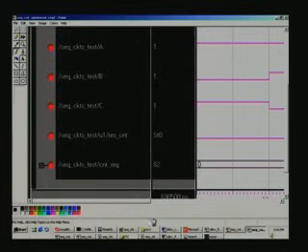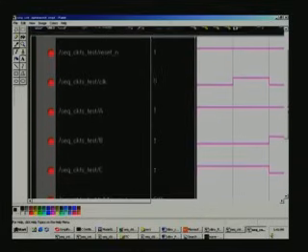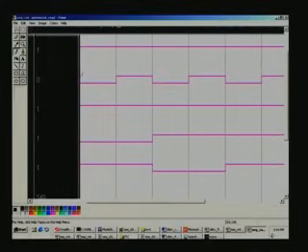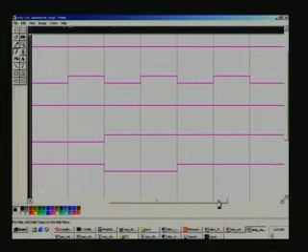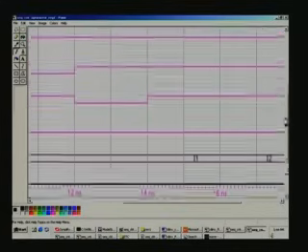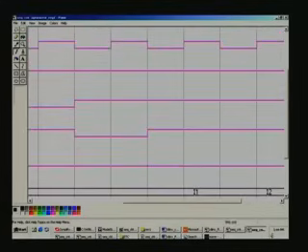Now let us see, is there a clock? I think I have forgotten the clock. Oh no, it's there. So the clock is this waveform here, and the very last one is the counter, and unfortunately you can't see both. Can you? With difficulty you can, right? Now notice this here. At this positive edge of the clock, the counting is not happening. It is only after a shift that it has happened.